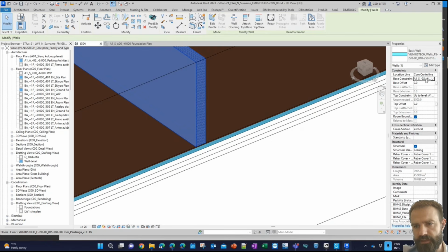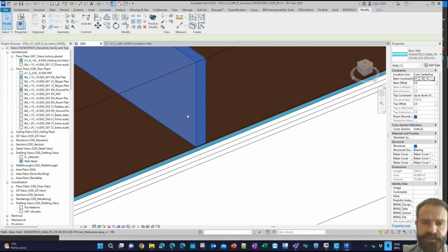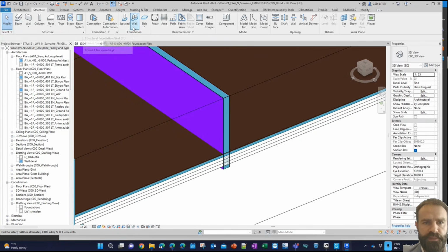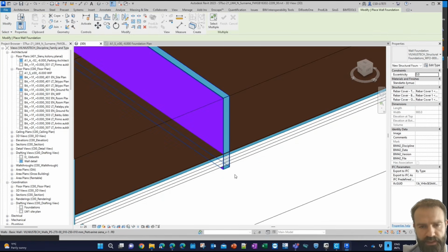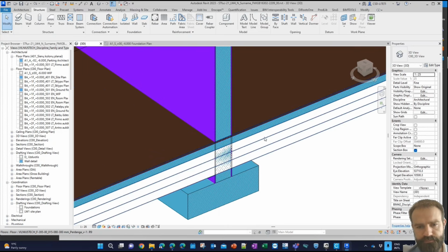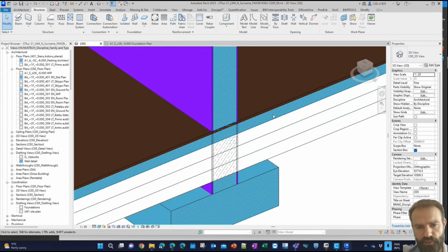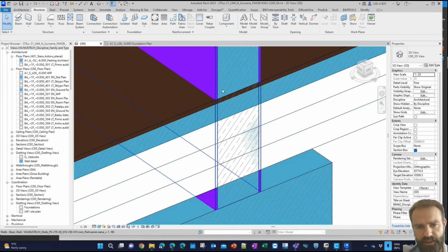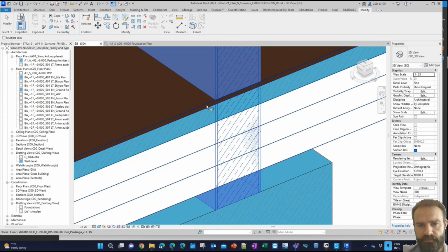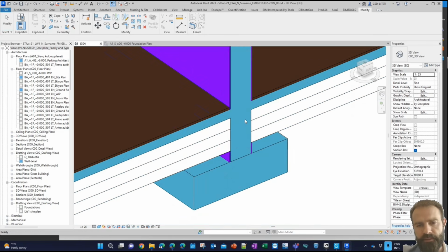So it means I select minus 6.5 meters. And for this wall, I also need foundation. So I update my model by providing missing foundations and select the wall, and I have foundation. Now I need to solve this problem because I have a situation here. So to solve this problem, I go to join and select elements and I join it.